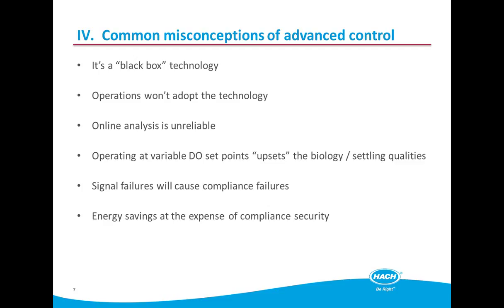In practice, the controller will improve the settling qualities as over-aeration doesn't occur at times of low load, which often leads to filamentous bacteria dominating. Our sludge controller will improve biological conditions still further, but that's another topic and another presentation. Signal failures will cause compliance failures.